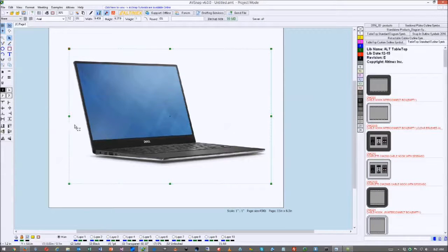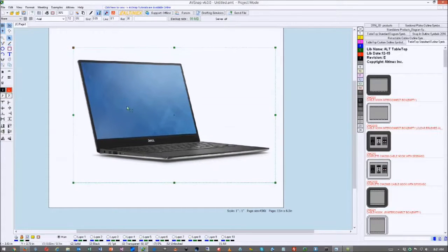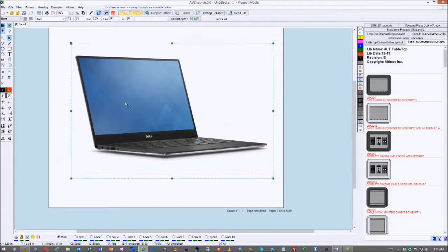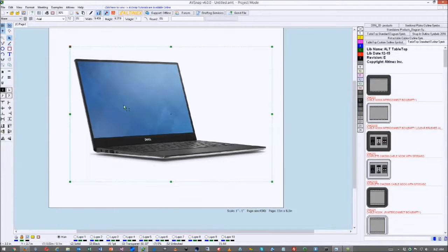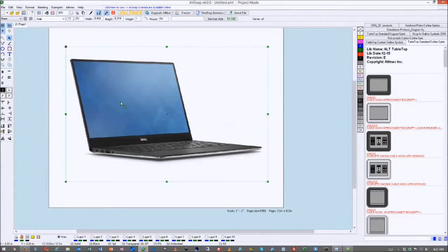All right, so let's come back in here, and we're going to outline this symbol and create a hand drawing. First, I want to make the line red as a default, because doing it red will make it easy for me to see. Now the next thing I want to do, and this is an introduction to layers, is put it on the background layer so it doesn't move, so I don't accidentally select it. You can definitely press U and lock it in place so you can't move it, and you can see that the mouse pointer shows there's a lock. But the point is that you don't want it to be even selected as you work on it.